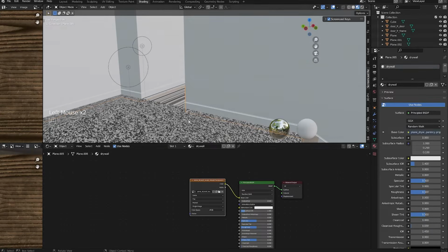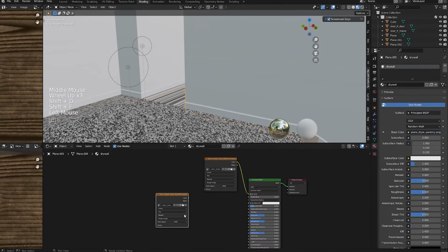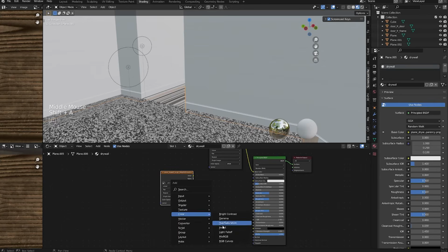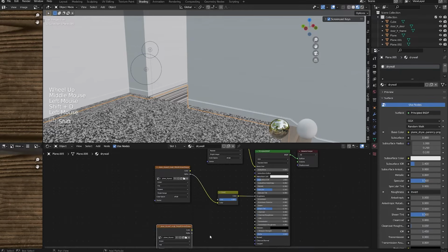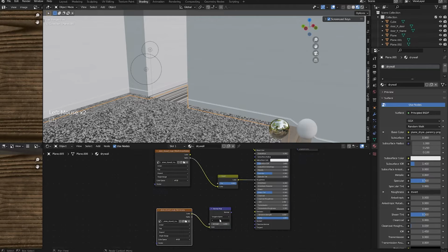So this is similar to the first texture that we used. Duplicate this image node. Let's find the metallic smoothness. Let's go to color, invert, because that smoothness information is in the alpha, and smoothness is opposite of roughness. So we need to invert it and bring that over to the roughness. Let's duplicate that. Let's go to vector, normal map. Let's find the normal texture, bring that in. Color to the normal map here, and let's change this to linear.